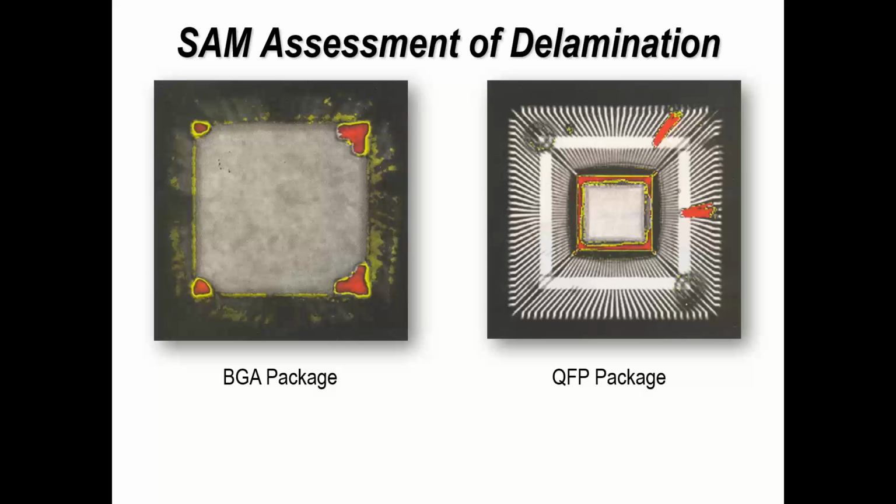And what you can do is you can find the level where you've got potential separation or voids or cracking, and just look at that level. Whereas on these are picture superimposed on picture. So it depends on the sophistication of the tool that you're actually using. But it can show up and demonstrate to you whether the component has been damaged or not. And the easiest way is comparing it with a brand new part compared with one that you're investigating on a board.